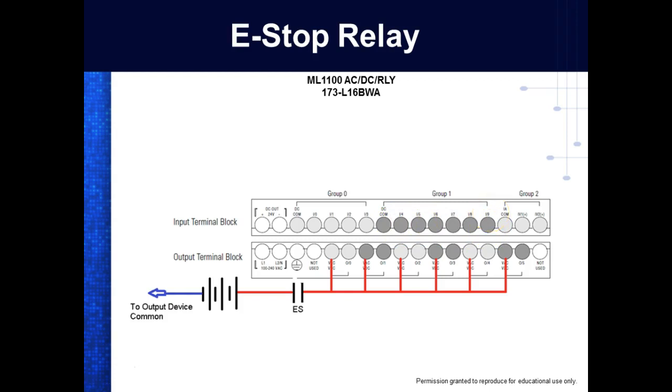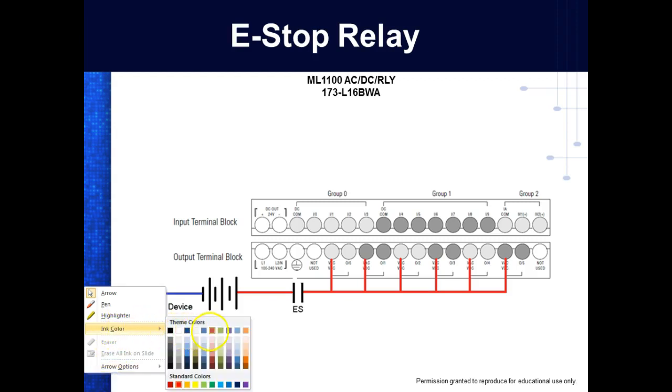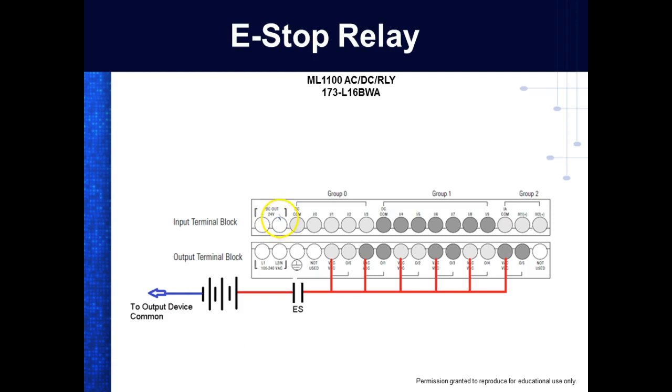So what we can do on this PLC is we can set these groups of inputs. We can set them up for either syncing or sourcing, depending on what we use for a common for the PLC. So if I was going to set up a syncing input, then I've got one of 2 options. If I'm not using high-powered sensors, then we could just come over here and take our minus, and then I would go to this common, and then I would come over here and I'd run that to this common.